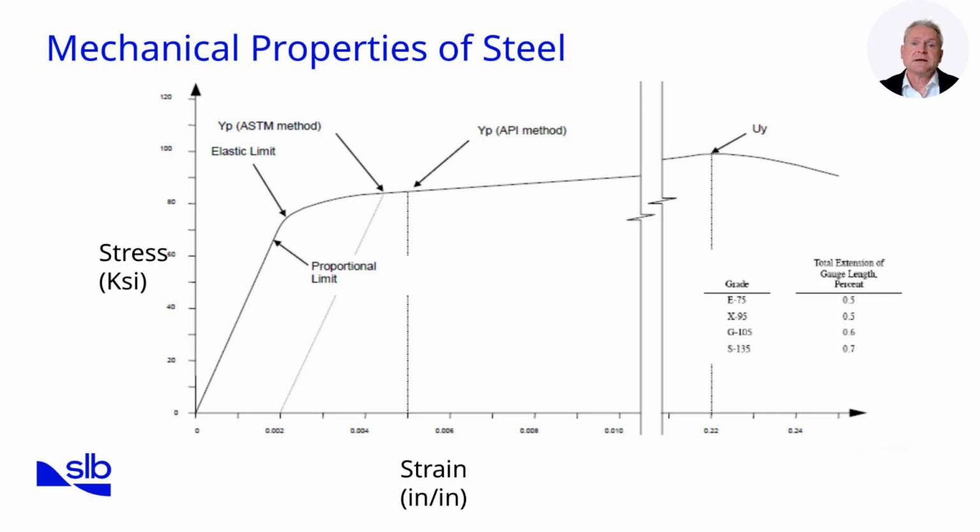Higher strength grades allow for deeper wells and greater torque, but they may also be more brittle and less tolerant of surface damage. Temperature and environment also play key roles, as high downhole temperatures reduce steel strength, while corrosive fluids promote cracking and pitting. Understanding the stress-strain curve allows engineers to set safe operating limits that prevent overload and ensure the pipe operates well below its yield point.